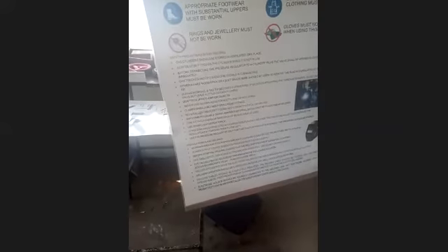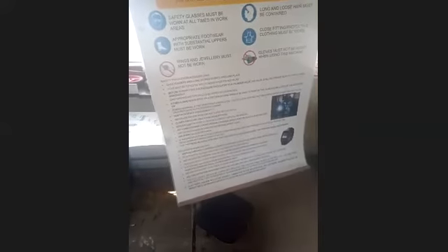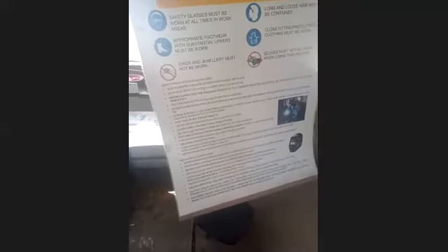Before starting welding, ensure that welding equipment is properly earthed. One should not look at the electric arc with naked eye. Use a helmet or hand shield.